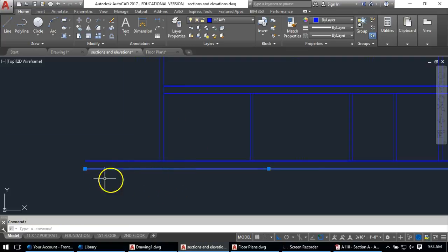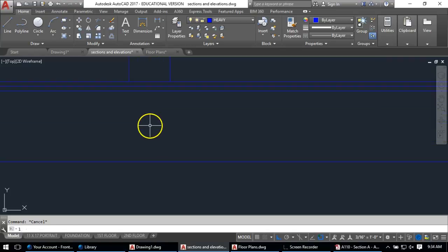Basically, I'm going to take back the ceiling height, just pull it in a little bit. I can extend it later, because what I know is going to happen is right at the edge of this wall. So I'll draw a line down, and I'll pull it down this way. I'm going to have 2 by 12 coming sort of at me. This is actually in cut, so I'm going to offset 1.5 inches to get this.